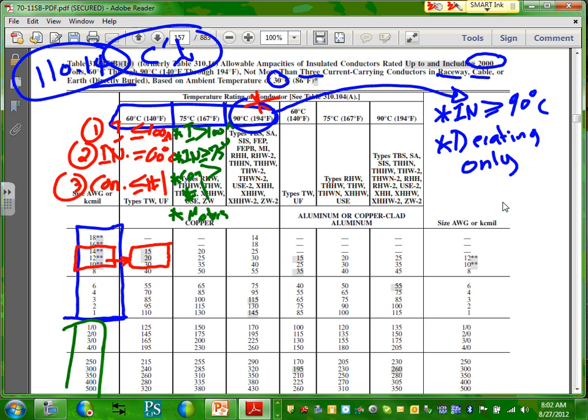You're going to get into a situation where you start derating with number 10. Because look at this. I'm just going to take number 12. Look at number 12. How much current can number 12 carry? Can you guys see it? 30 amps. Can I pull 30 amps on number 12? No. Why? Small conductor rules. And second, number 12 is a conductor less than number 1? Yep. So where's my default? 60 degree anyway.